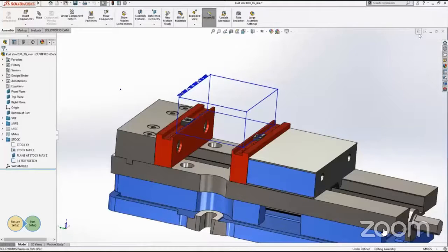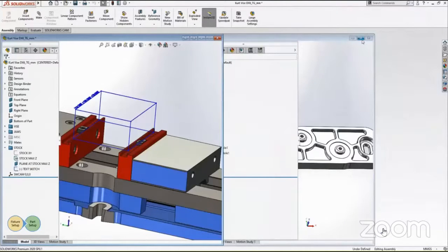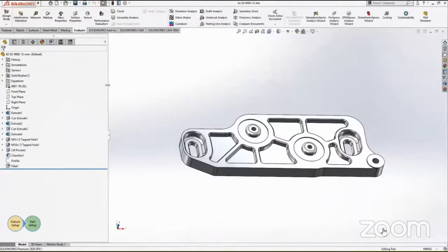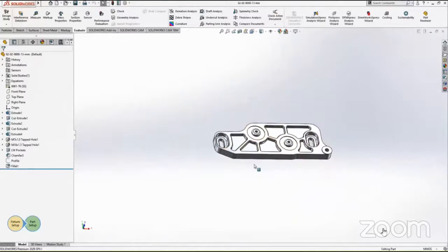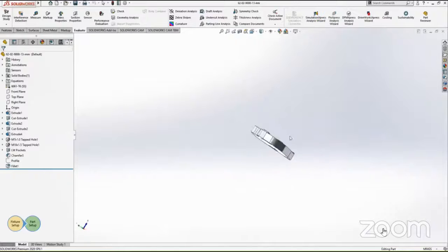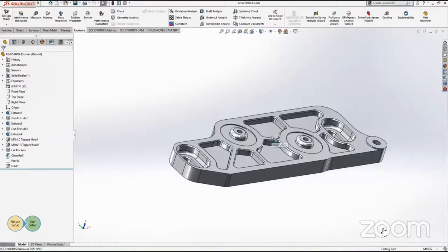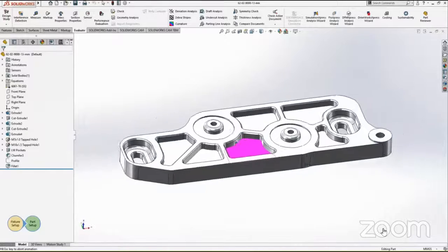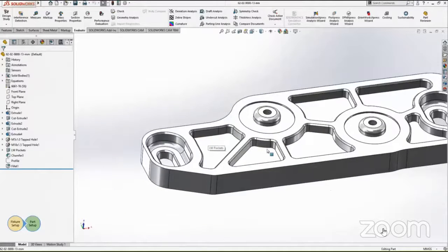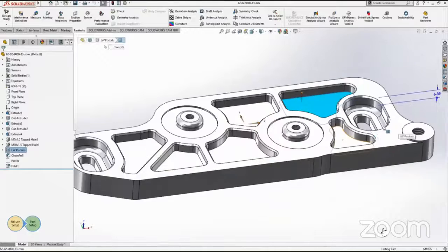All right, so let's look at the CAD file that we have to perform machining on. This is the CAD file, and we want to machine a part, and it should give the result in this design and this shape. So before we begin the CAM process, we have to analyze what type of features are there in our CAD design. We have pockets, and there are almost 6 pockets. We also have some bosses in our design along with the chamfers.